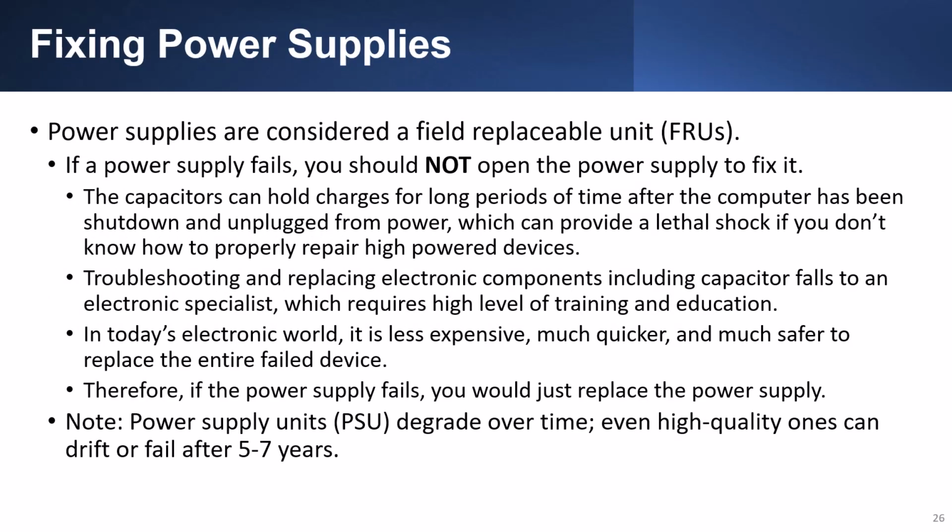Power supplies are considered field replaceable units, or FRUs. If a power supply fails, you should not open the power supply to fix it. The capacitors can hold charges for long periods of time after the computer has been shut down and unplugged from power, which can provide a lethal shock if you don't know how to properly repair high-power devices.